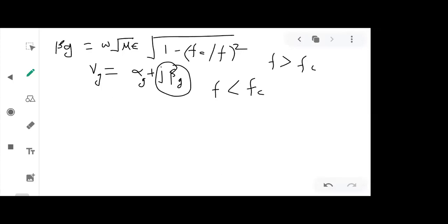So when the beta becomes real in nature, it means that the wave is now facing attenuation, and that particular signal cannot travel inside that transmission line. So using this relation also, you can prove that a waveguide actually behaves like a high pass filter. But you have to remember that this is the formula if you are interested to calculate the propagation constant, or the phase constant actually.